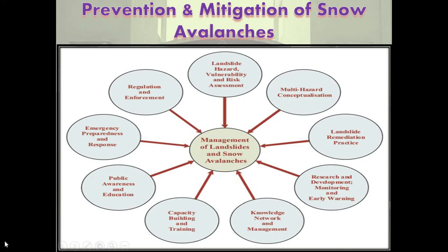Since avalanche-prone areas can be identified, the safest and probably the best mitigation procedure is to avoid construction of buildings or any type of structure involving winter use in this area. Agriculture and recreational activities that take place during the non-avalanche months are relatively safe. Other uses that could be considered are those that do not involve permanent unprotected structures in the avalanche path, or those that could be moved or closed down during high avalanche risk periods.